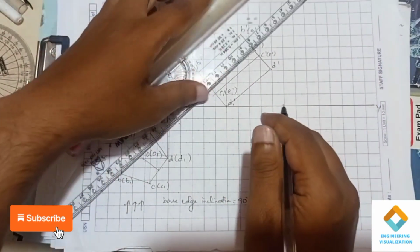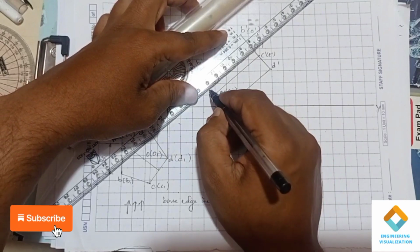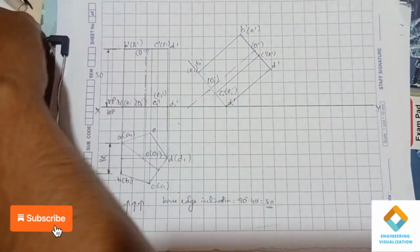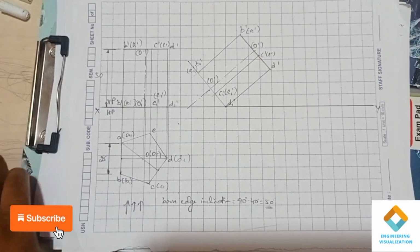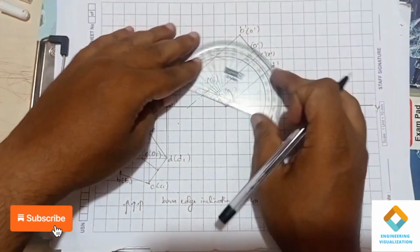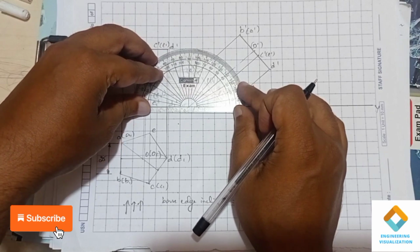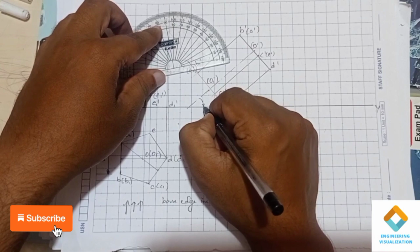Okay, now we have to extend this axis to show the angle, because the angle of inclination to HP they have mentioned with respect to the axis. So we need to show the angle for the axis only here. Okay. You can cross check the angle using the protractor. So it is exactly 40 degree. Okay, that's the angle given in the question, 40 degree.